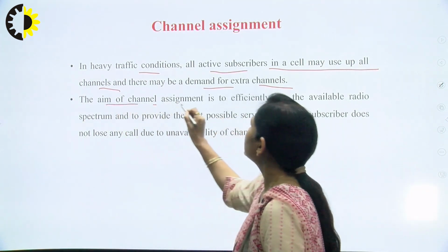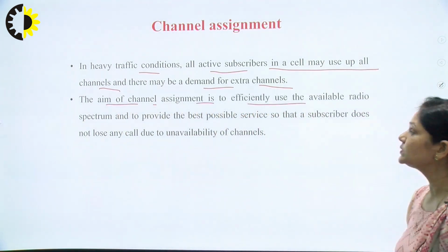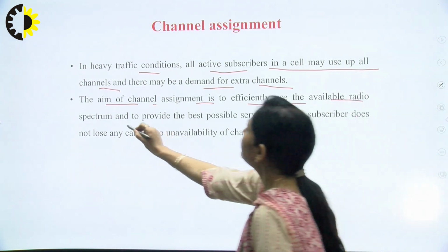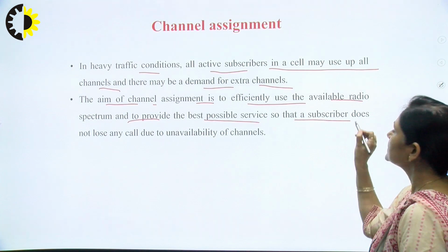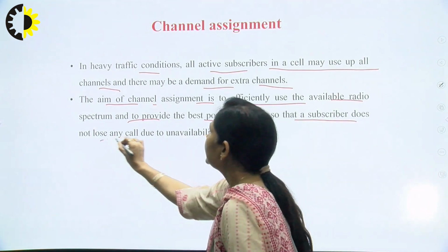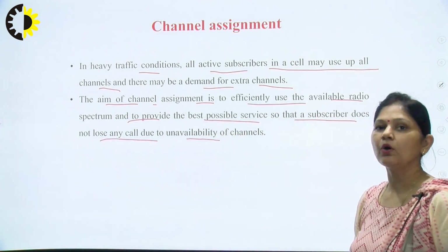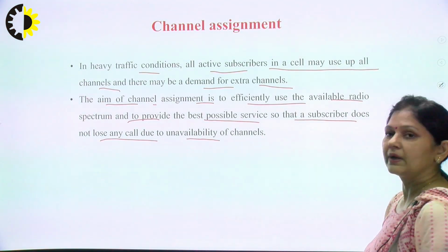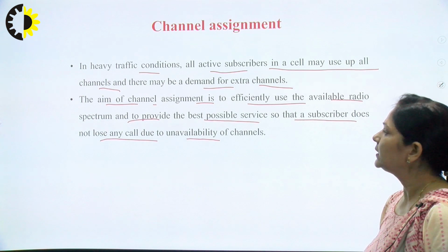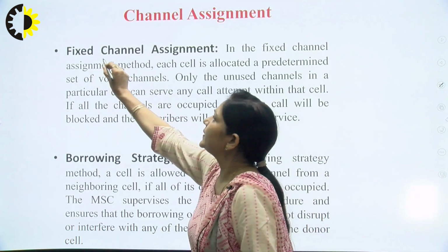The aim of channel assignment is to efficiently use the available radio spectrum and to provide the best possible service so that a subscriber doesn't lose any call due to unavailability of a channel. So this is the reason that we are discussing channel assignment. Now the various strategies for channel assignment include: first is fixed channel assignment.